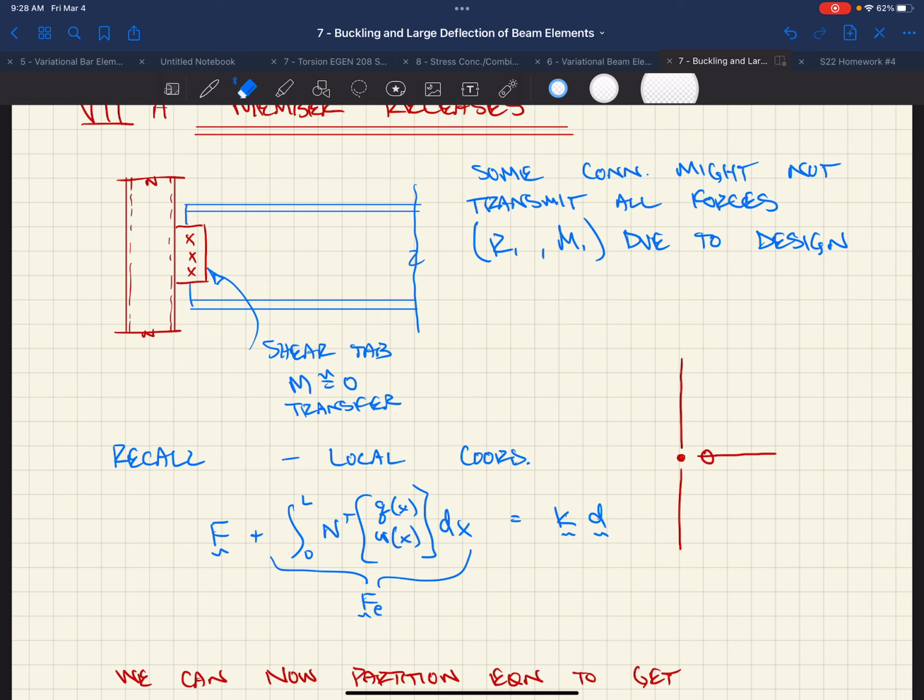But also the big thing that happens when you start looking at lateral forces and you're starting to drag loads, like axial demands and collectors and chords, right? So now your brace frame might be 3 or 4 bays down here, and you're trying to drag all that load out of the diaphragm. By the time you get to the 1 or 2 beams right before the brace frame, those loads can get pretty big. And so now you're trying to pull and push this shear tab into the wall of the column. I mean, you're really in trouble. So you end up saying, all right, I'm going to put this shear tab through it.